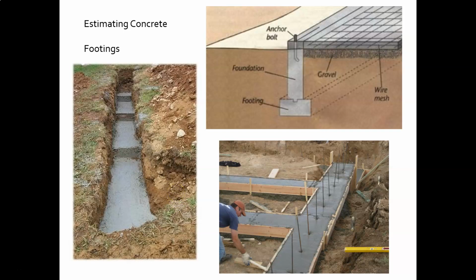Basically, this is what supports, or takes the weight of the house, and this is what distributes it into the earth. The footings. This is the very first thing that's installed. So these are step footings. Here we see a footing right there, and so we would be multiplying its height times its width times its linear feet. And that's what we would be doing here. So we'd have to calculate all these linear feet.